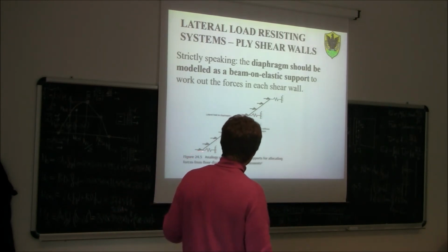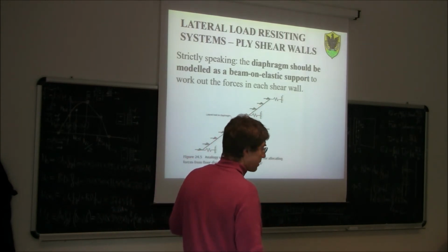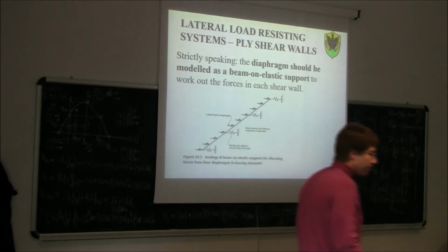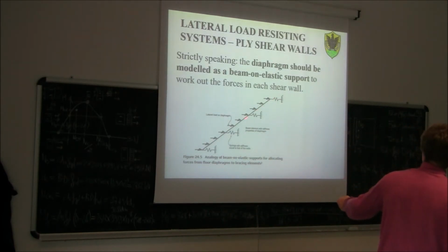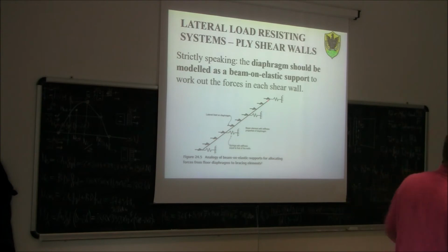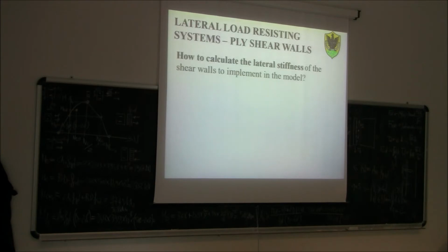And then I should model also the flexibility of the diaphragm itself, which is very complex, because the diaphragm in this case is modeled as a continuous beam that rests on a number of flexible supports schematizing the vertical walls.